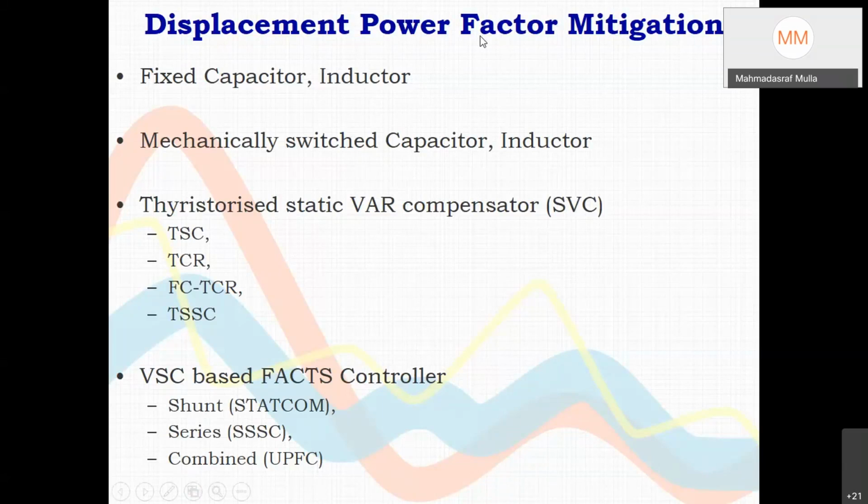Yes. So if we imagine some heavy motor continuously running and the load at the shaft of the motor is continuously changing, this thyristor based arrangement will not be able to rapidly change the reactive power the motor requires while working with different loads. It will require several cycles to calculate what reactive power the motor needs and then switch on some capacitor or reactor to support that.